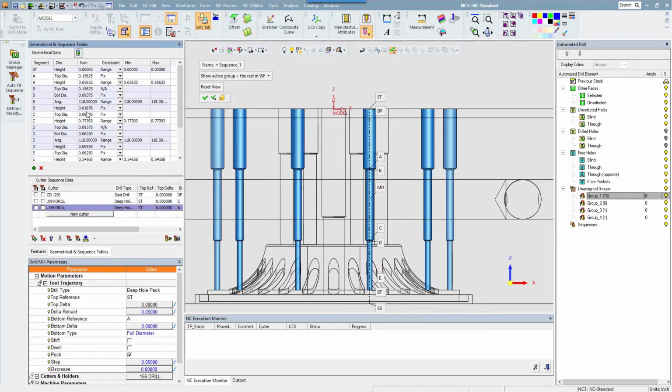So if we set this up right, it should cut many different parts, even if the geometry is slightly different in, let's say, length, but not necessarily size. Or if we set up ranges, it can be different size and length. So what we'll do here is we'll start at the top. So the ST anchor, the height, and the nominal size.